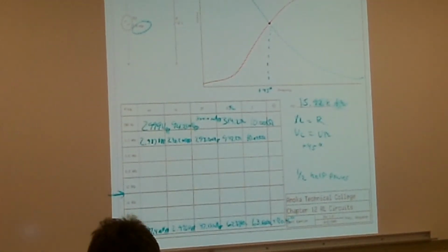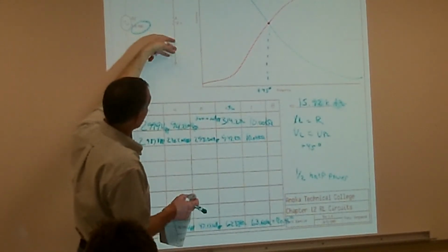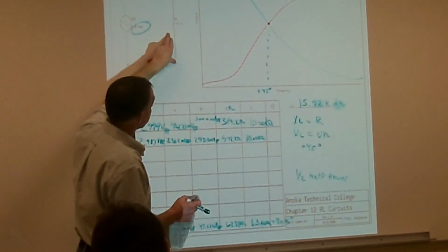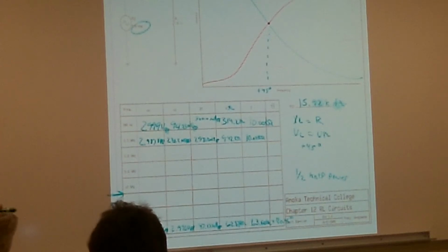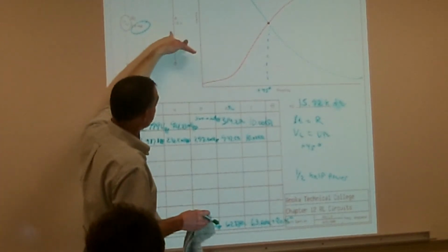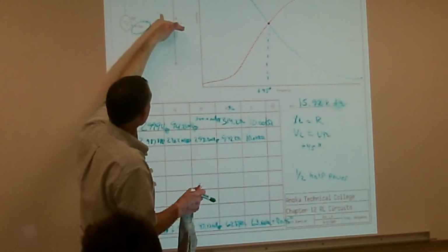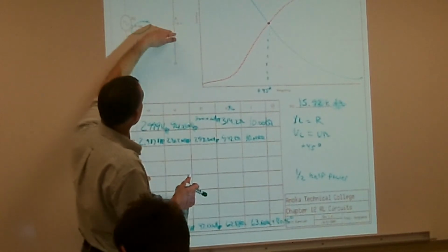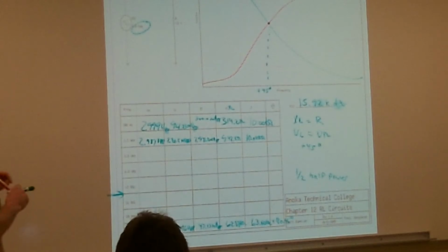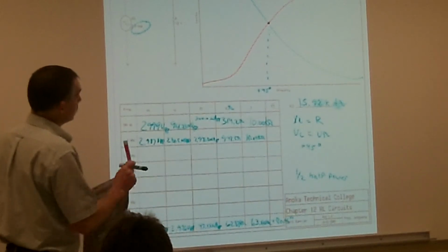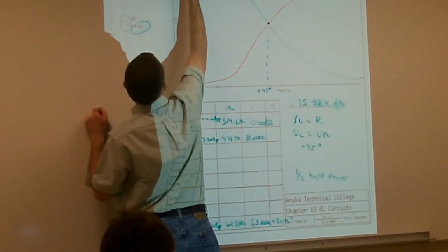basically what we have is these. Now we're using these very simple high pass or low pass filters. We might have a circuit where we only want certain frequencies to be allowed through, and it all depends on which one you're measuring across. You're going to measure across either your inductor or your resistor when you're using these as filters. If I only want low frequencies going out of my output, here's my output right here, that's point A, that's my output.